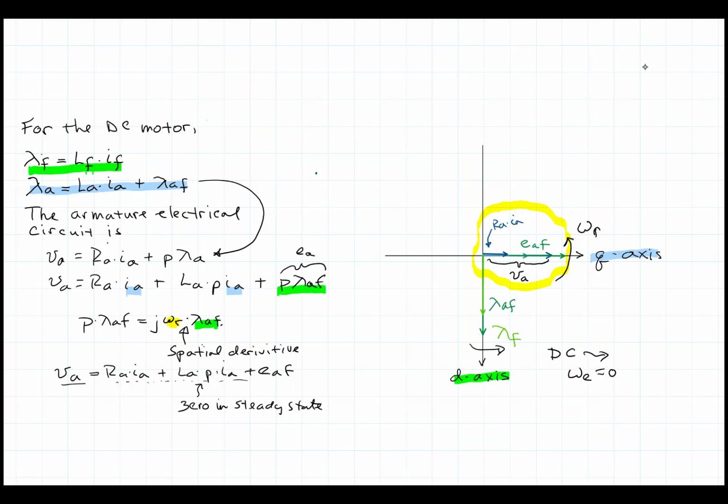Because of the Lorentz force law, we've got a moving rotor interacting with the field with these armature windings on it, and then the commutator and the brushes are reorienting the coil current through the coils to maintain this quadrature relationship. But everything's happening on the rotor.